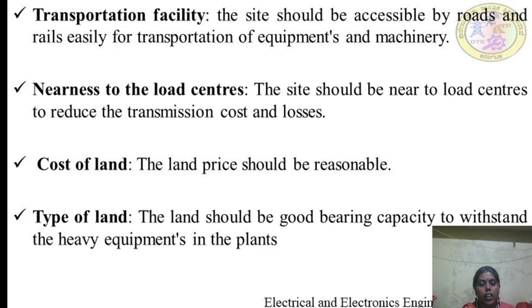Next is nearness to the load centers. The site should be near to load centers to reduce the transmission cost and losses.